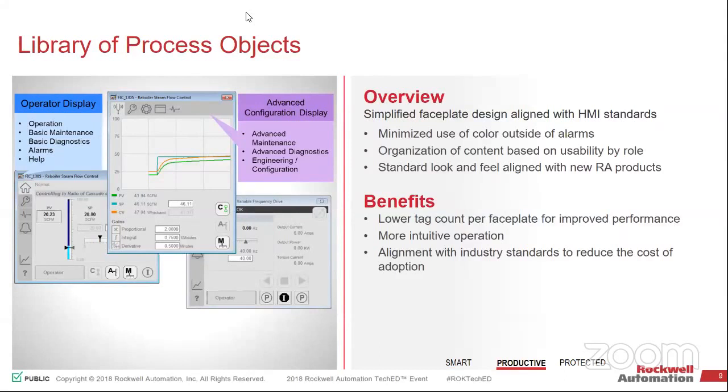It is very grayscale, and you'll see it when I show the demo. The only pieces of it that have color are anything that's moving. If it's a variable that's changing, like the temperature going up and down, that might be in blue. Everything else is going to be grayscale. And if you see a bunch of color or anything blinking, that should be an alarm, or a reason to open up the block and figure out what's going on.